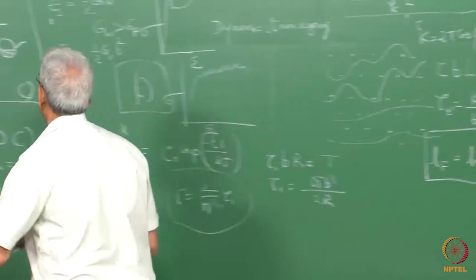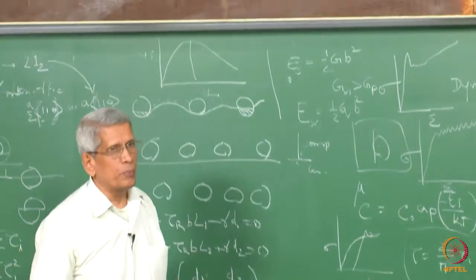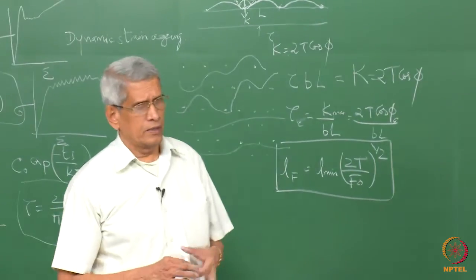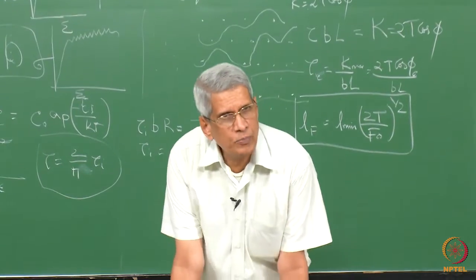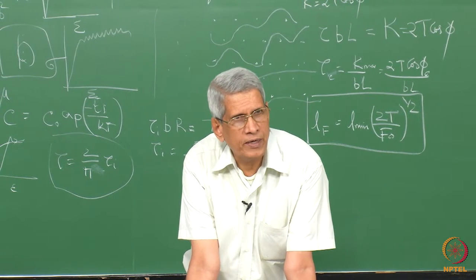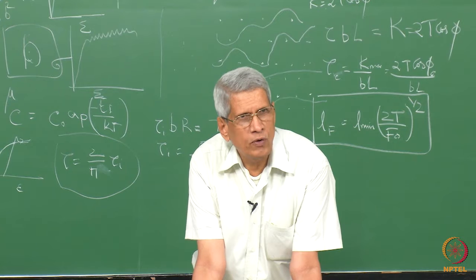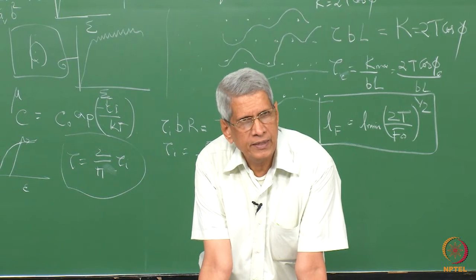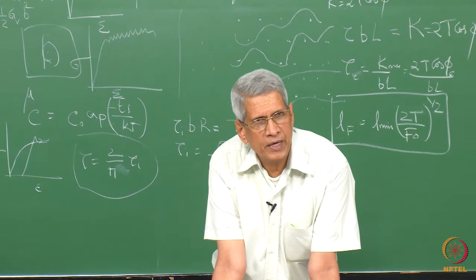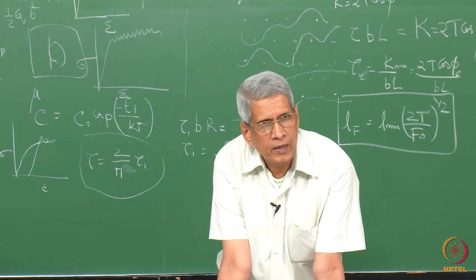So from this region, looping is essentially going to be the predominant mechanism. Suppose it's not a second phase particle which is produced, but dispersion hardening. We have put an oxide particle into it. Nowhere can the dislocation enter and cut the particles. In such cases, only looping will take place as the main mechanism of deformation.